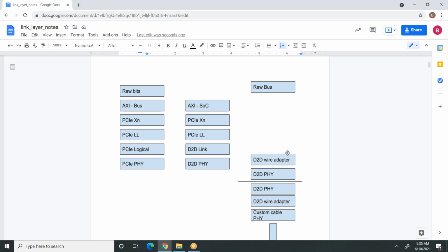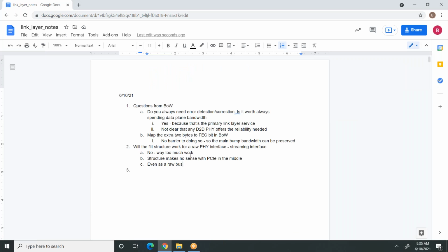I think, Arthur, for our version of a link layer, we have the services of the link layer, and then we have this idea of LPIF on the far side, where we map the application interface to lanes. So this is fundamentally compatible. If you decide that you just want some sort of wire interface and you don't want the services of the link layer, then the link layer comes out, and all you're left with is your application interface coming in, and then you're mapping to the LPIF. You just have a mapping from application to lanes, so flits to lanes.